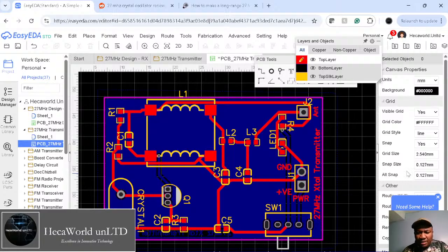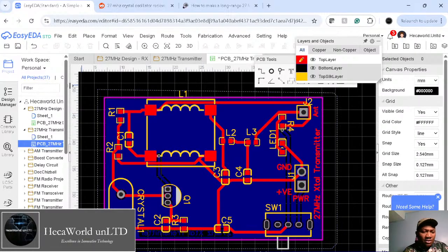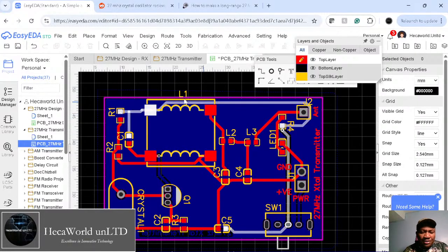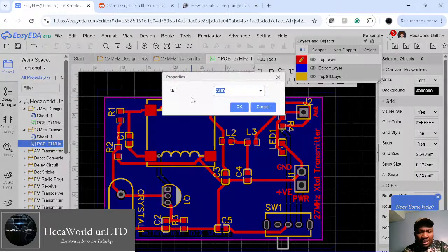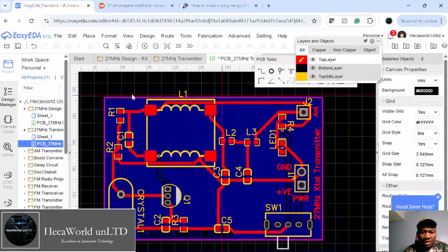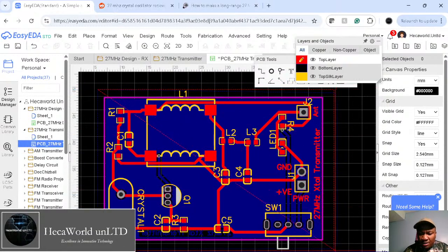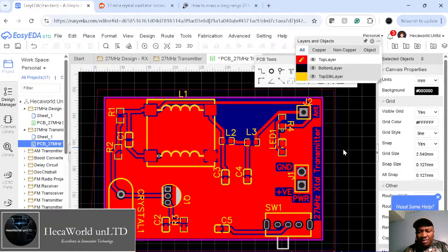Okay, I think that is fair enough. If you want to put more text, you can go ahead and do that, but we don't have to. Now we're just going to put the ground in again. So I'm going to do E, click on OK, click anywhere outside the board, and then on all four corners of the board, then escape, and this should be applied. All right.